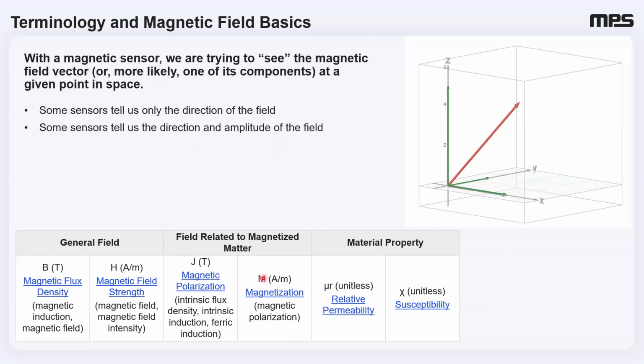Lastly, I'll just mention Encyclopedia Magnetica. This is where I got this table from. It's a really nice online magnetics source. It's got a good treatment of magnetic terms and variables and some of the confusion that's been created by conflicting usages in past literature. These terms were the bane of me when I was in college. What's the difference between H and B? You'll often see people call B the magnetic field strength, and we're starting to see a push in the field to correct some of the ambiguity that's been present in the past and standardize terms, and I think even eventually standardize units to the SI units. That's what I'm going to use today, and whenever I'm talking about field, I'll be talking about the B field, the magnetic flux density.